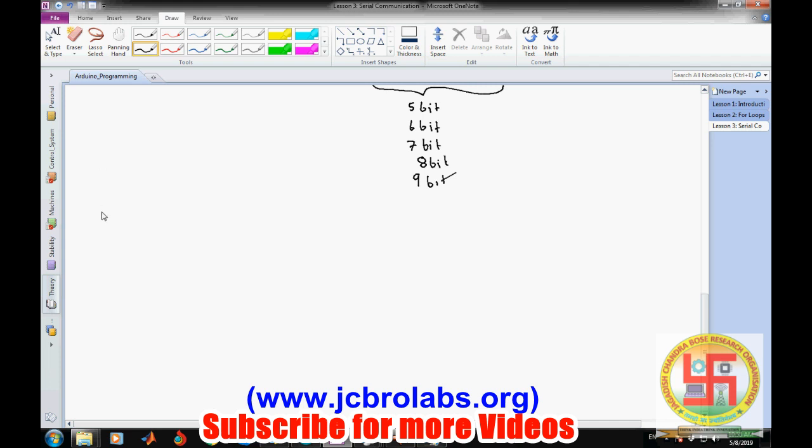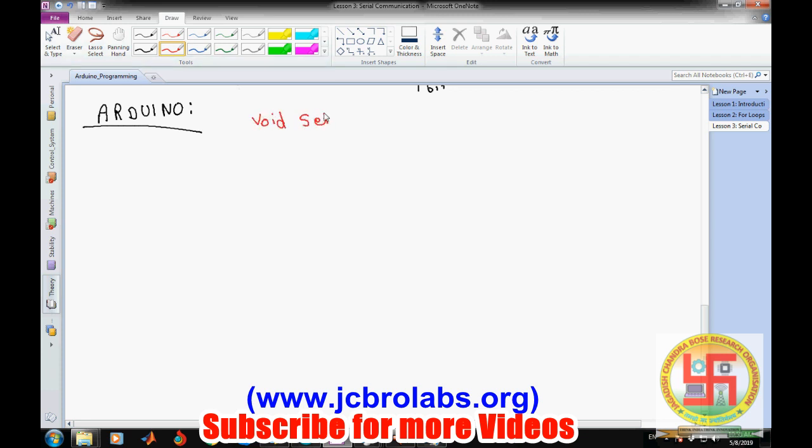So now coming to Arduino, how can we define it? In Arduino, most of the time it is already defined. We use 8 bits of data, 1 start bit, 1 stop bit. The only thing we need to define in Arduino is the baud rate which we are going to use. That is defined in void setup. In void setup we will write Serial.begin. This is the command, and in it we define a 9600 baud rate in this case. We can also define several other parameters as well.